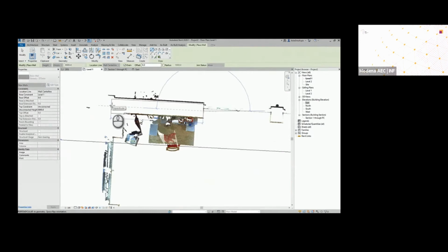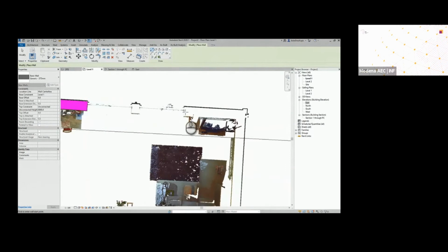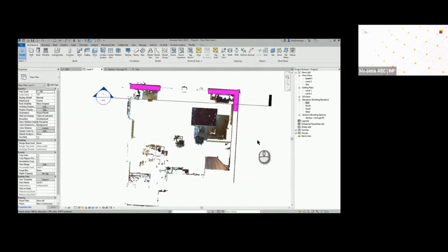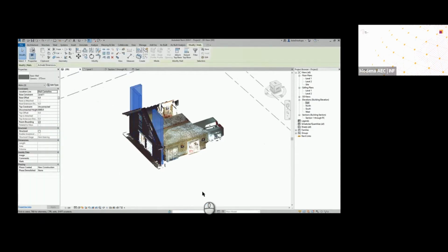And of course, if you're utilizing other toolsets like the tab button, it is easier for you to go and align the walls. This can happen at any point. These are just stock standard features that already come with Revit when you are utilizing point clouds in your modeling skills. Note that Revit gives you even more control over your point cloud, not like in any other type of design package. The idea here is that in any view, I can go here and manipulate my point cloud.